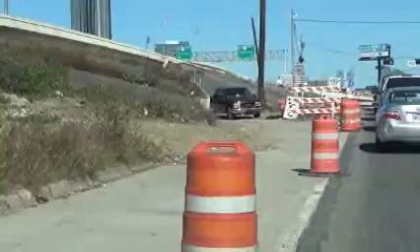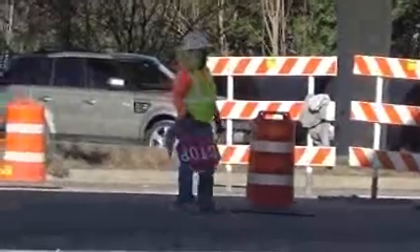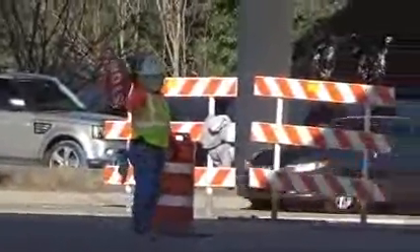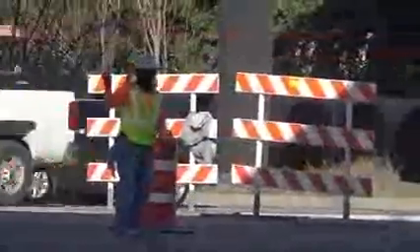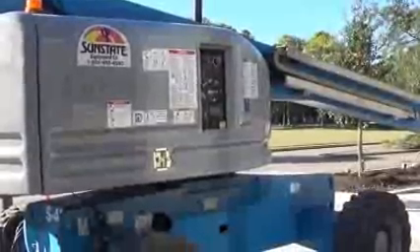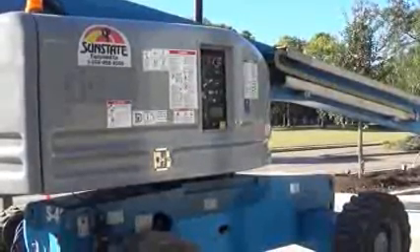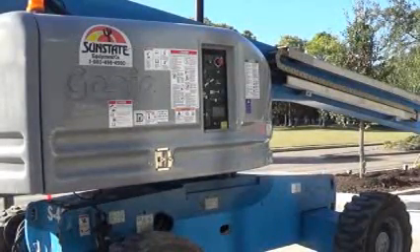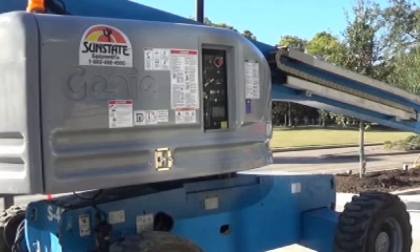Use warning cones, road signs, and flaggers to ensure the safety of personnel when loading or unloading an MEWP on a public road. At the end of the workday, the MEWP should be parked in a secure area or in a supervised area inaccessible to unauthorized persons and the keys removed.